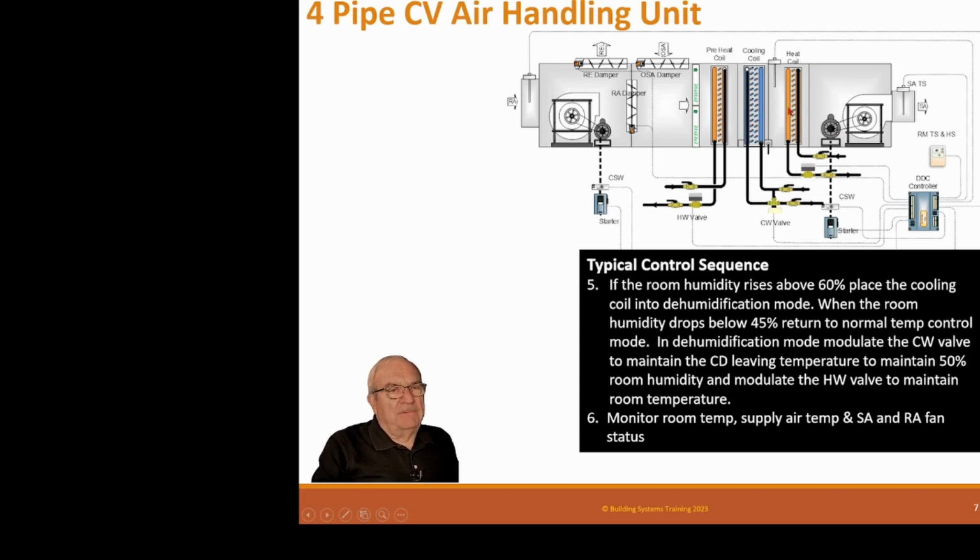Now, because this coil is there, we're reheating it down here. That is an energy problem. If we cool the air all the way down to as cold as it'll go, maybe it'll go to 48 degrees, and then we're going to heat it all the way back up so we don't freeze the people. That's okay as long as we need it. But if we don't need it, there's no reason to do that.